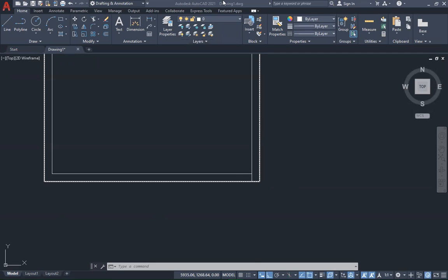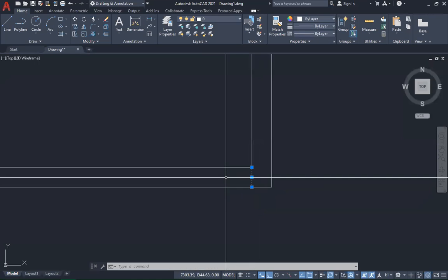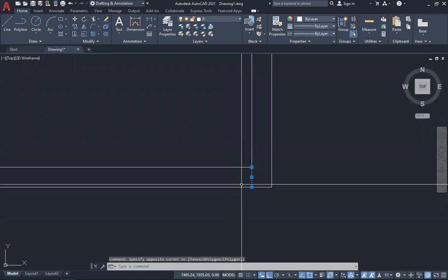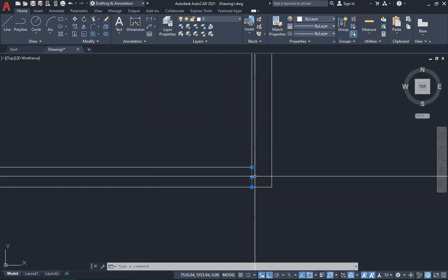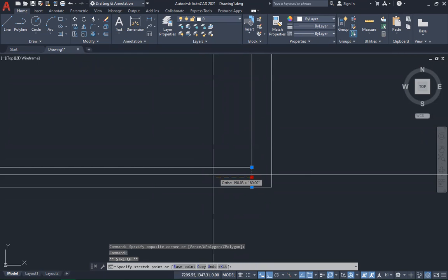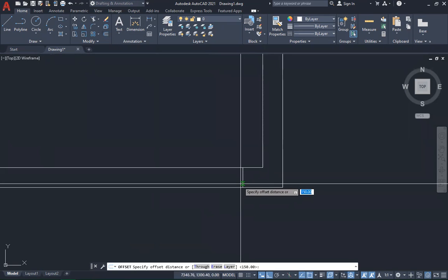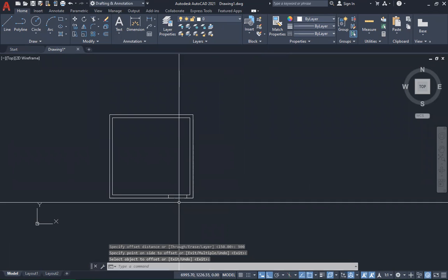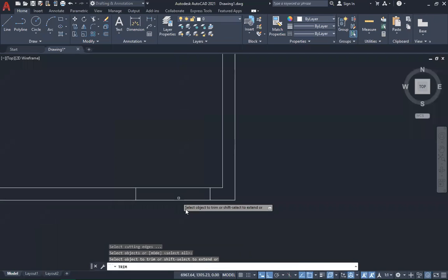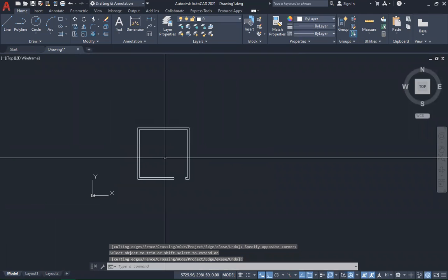And what I wanted to do with this is create a doorway. So I'm just going to highlight this and move it first of all by, let's say, 150 to just get a nice look. 150, yeah. And then I'll offset it again. I'm going to offset it by 900 for the size of the door. Yeah. So the doorway is being opened this way. So now I'm going to trim this. So we have that entrance, like so. This is for the bedroom.